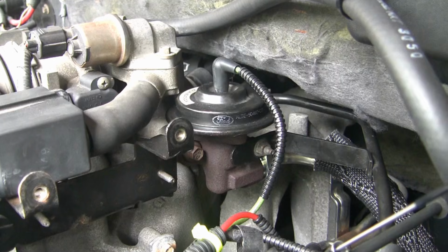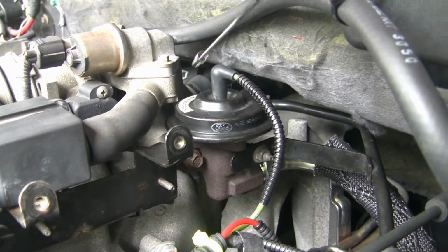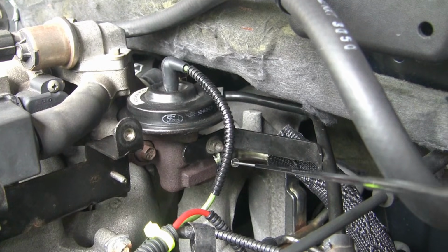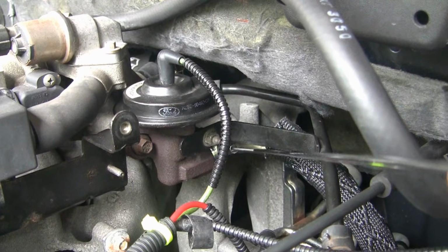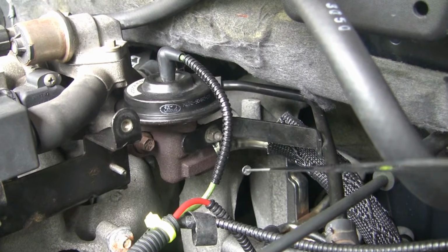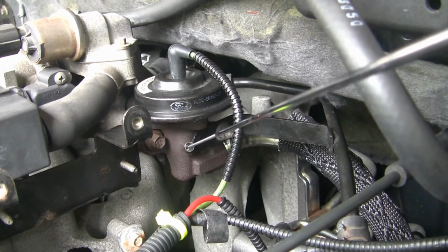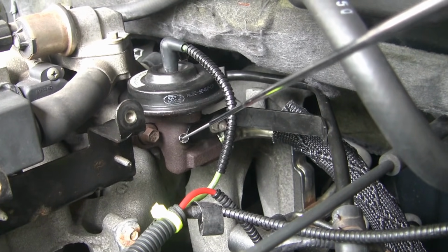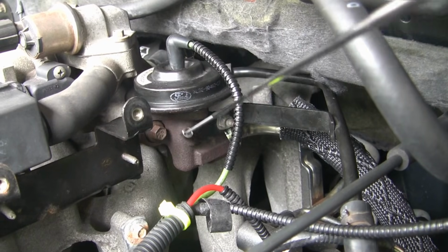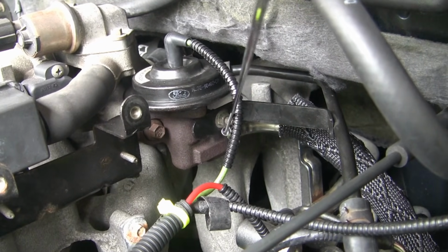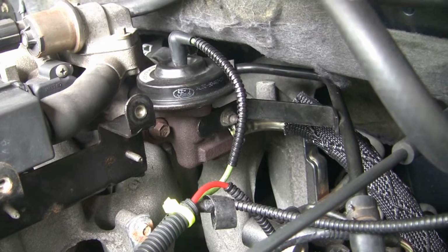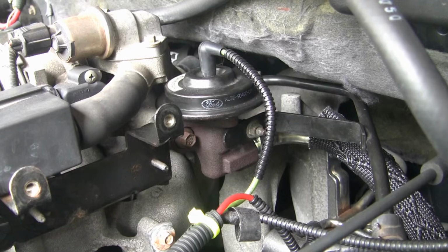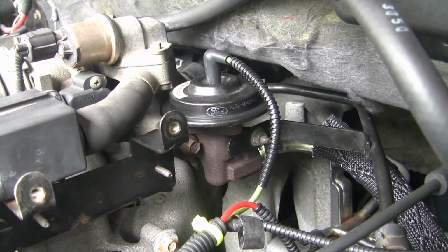Okay, some more detailed notes about how these components actually work. Start with the EGR valve itself. As we noted back here, this is the EGR pipe which brings the actual exhaust gas up from the exhaust system. And like I said, this is a valve, so what happens is your computer, based on some formula, some logic, which we won't go into here, which I don't really understand anyway, determines when to open this valve. And when it does, the exhaust gas goes into your intake manifold, your throttle body, and mixes with your air for the combustion process. And the theory is that it's going to reduce some air pollutants.